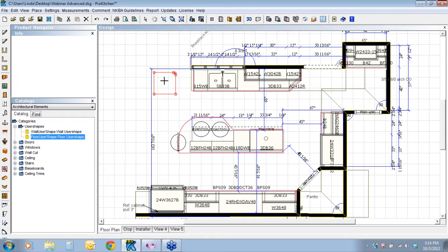Change the height of it to go from floor to ceiling and make it a post or a beam. And you can set beams on top of the ceiling. If you needed beams going across the top of your ceiling here, a 2x8 or a 2x6, you can actually just change that there.